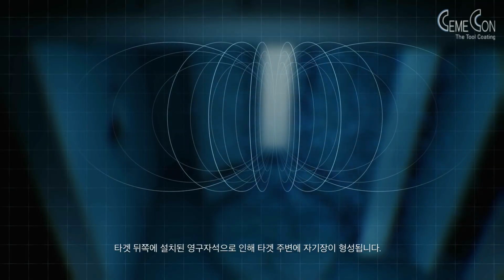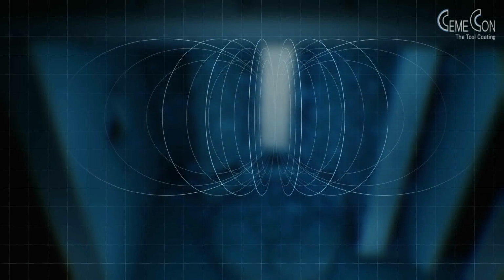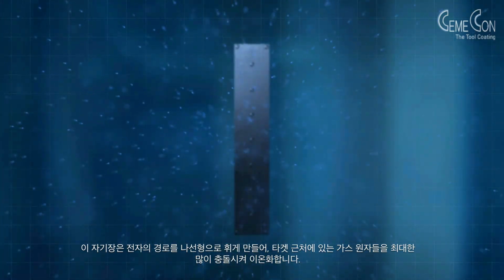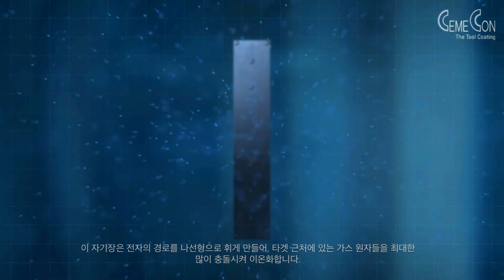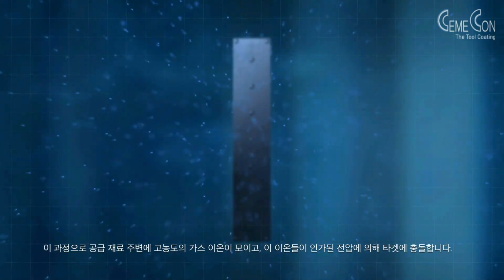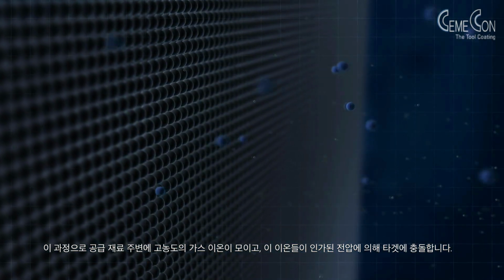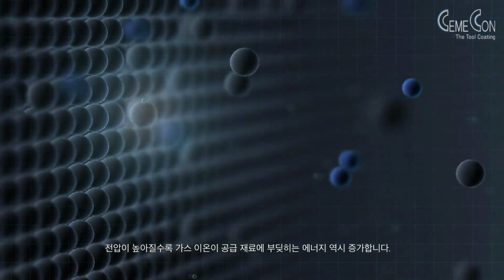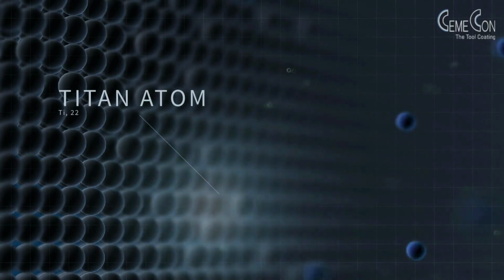Magnetic fields are generated at the target thanks to permanent magnets installed behind the target. These bend the path of the electrons into spirals so that they hit as many of the gas atoms located near the target as possible in order to ionize them. This creates a high concentration of gas ions near the donor material, which strike the target thanks to the applied voltage. The higher the applied voltage, the higher the energy with which the gas ions strike the donor material. This increases the sputtering rate and the amount of donor material atoms obtained.